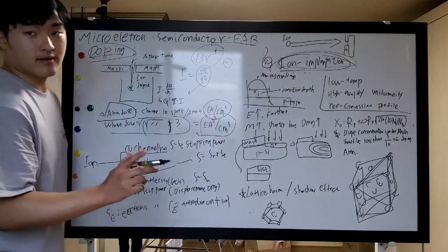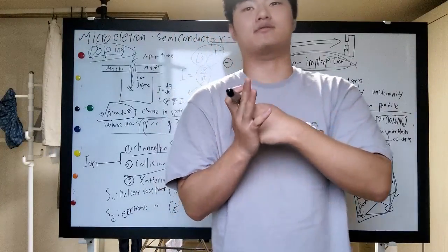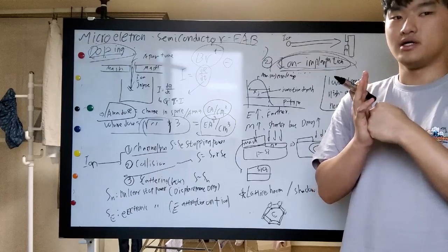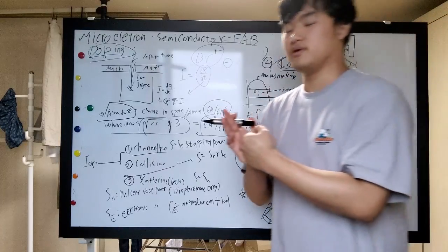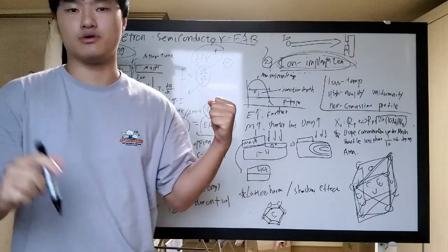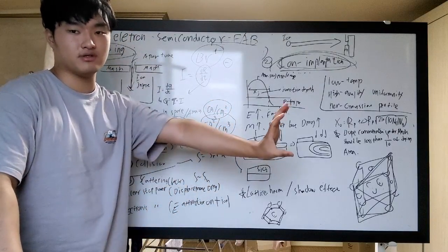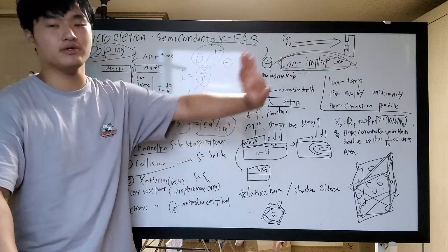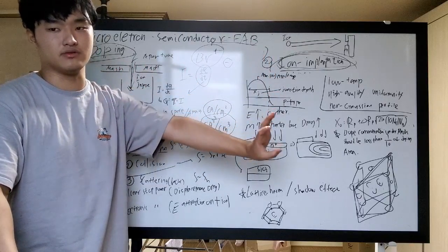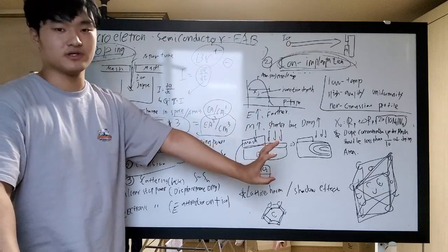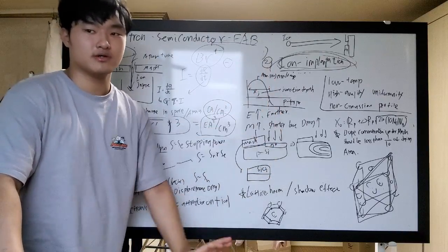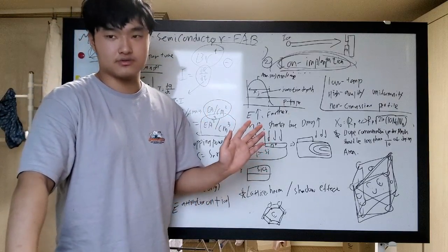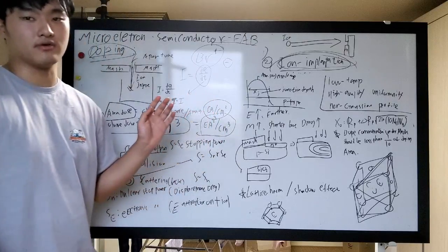And secondary collision just means impact between the nuclei and the implanted ions. The implanted ion has high energy, and when it impacts the nucleus, the nucleus will come out and its place will be replaced with the ion. But here is the problem. Collisions are okay if they hit just one time and replace the atoms, letting the ion stay inside.